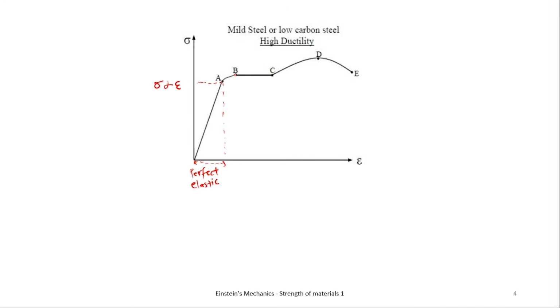So at A, you know that stress is proportional to strain. And at B, what is the difference between A and B is that at B, the stress is not proportional to the strain, but it is still in the elastic limit, meaning when we release the load from the bar, its length is going to regain. We try to stretch it.